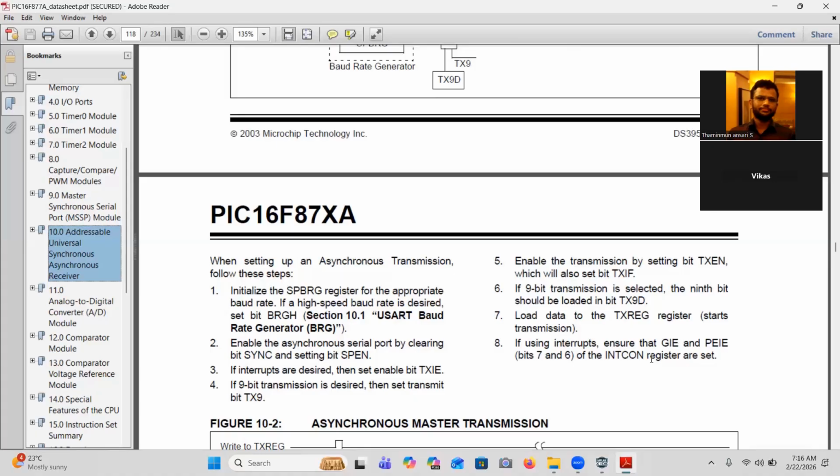The peripheral interrupts are the interrupts created by the circuitry. There are different circuitries, like timer circuitry, serial port circuitry, ADC circuitry. These are different peripherals. Every one of these circuitries can produce interrupts. To enable and disable them, there are flags or control bits.